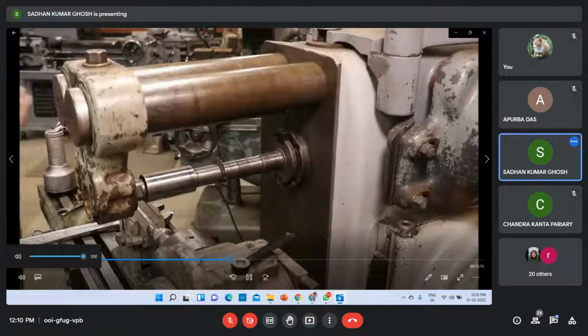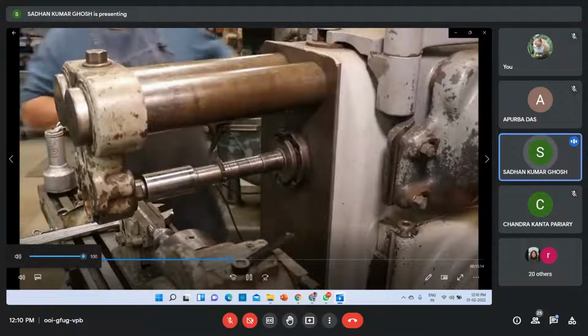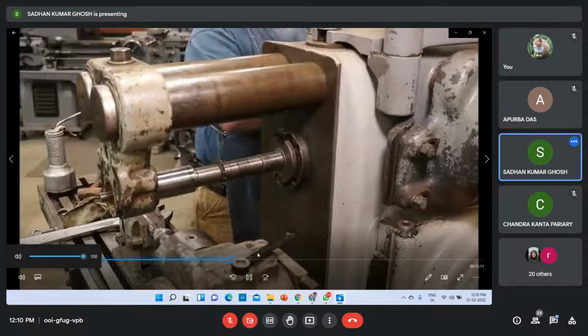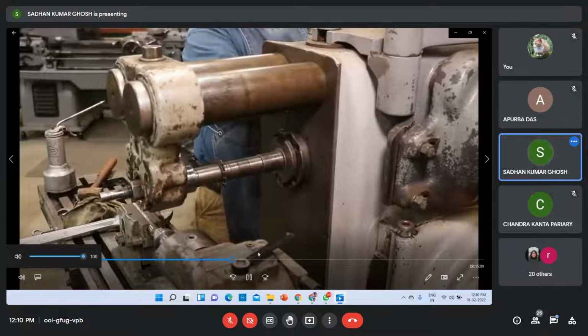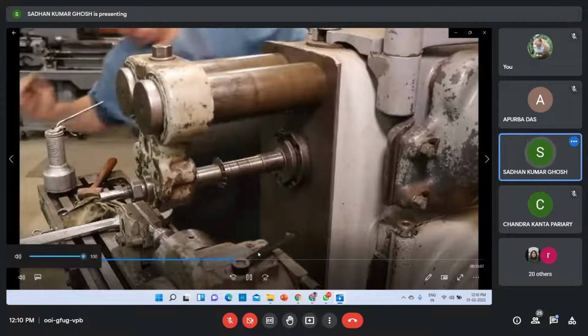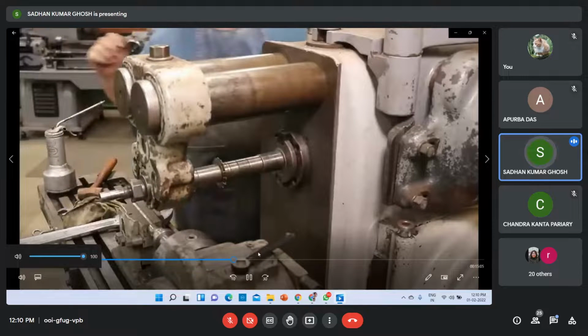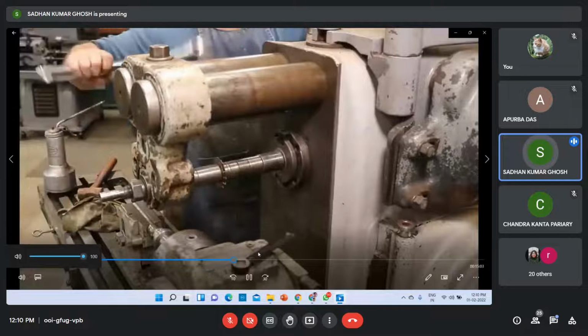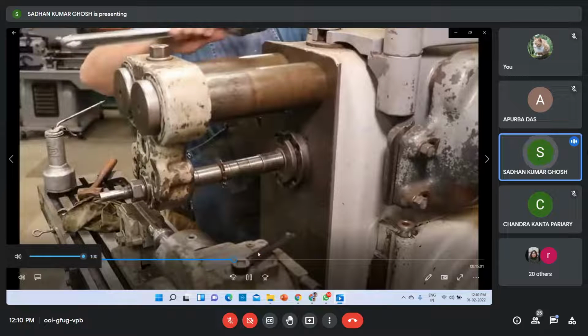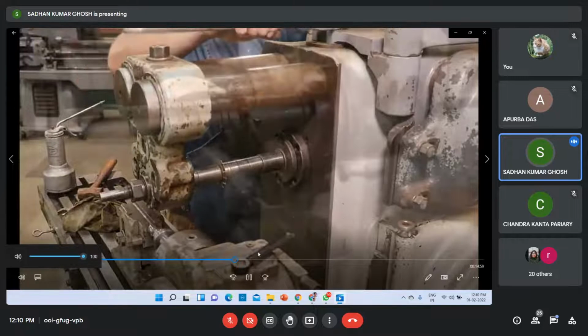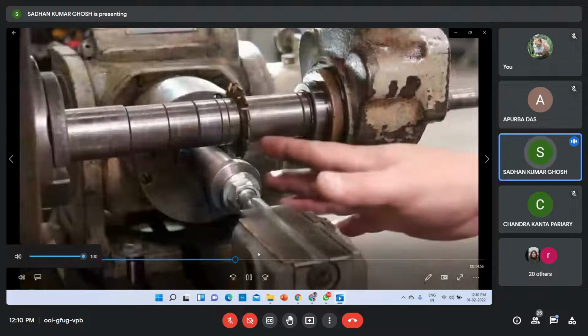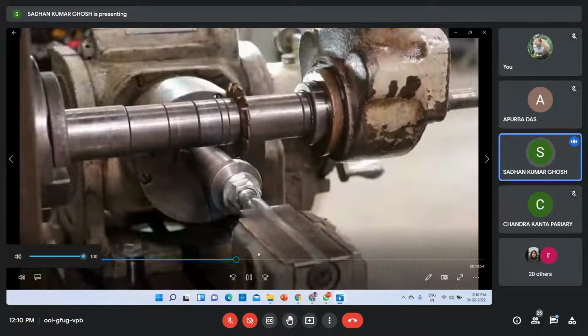Alright. Now I'll just pull the overarm support onto that bushing, slides up on there just as nice as can be. And that's good. And I'll tighten down the overarms on the top now. To the point now where I'll need to go ahead and get my cutter centered up onto the shaft here. We've got the involute cutter, everything set.